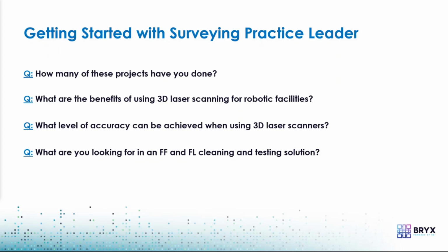Some of the remediation teams and the owners out there love Excel spreadsheets, and just to see all the numbers of the deviations that were found and what failed and what passed. Others like CAD output, which, if you approach the scanning right, as long as you tie it into the CAD coordinate system, when those reports come back, I'd like that CAD system to already be established so that I can just drop the results directly into floor plans. So now the owner or remediation team can say, okay, I can tell exactly where these are.